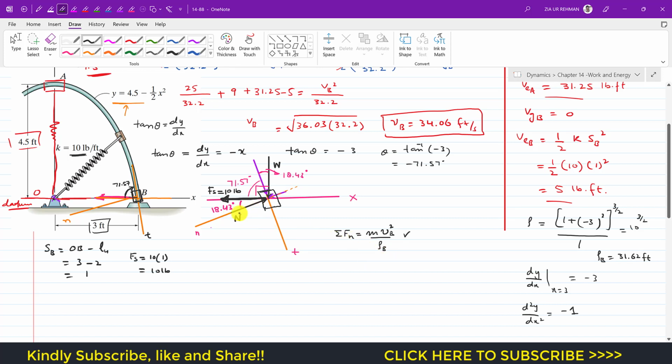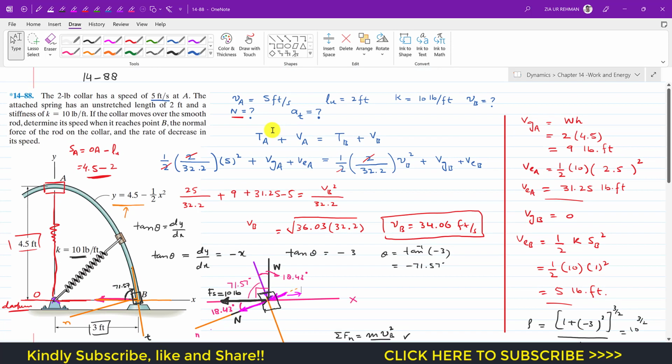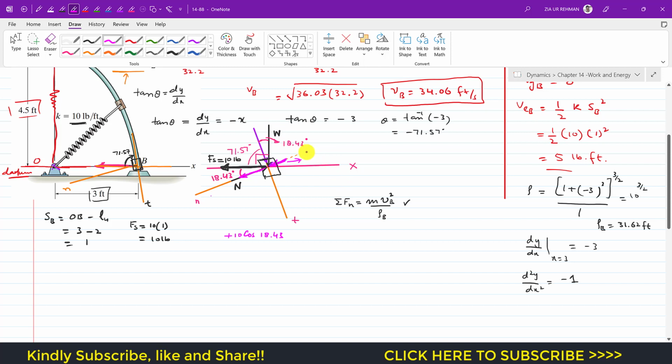So now we can apply this equation. The normal force is acting in the negative n direction. First let me resolve these forces. This spring force can be resolved into two components. One component is going to act in the positive n direction, like this. This is the cos component, so this is plus 10 cos of 18.43, and then this component of the weight. The weight is 2 pounds, it is given as 2 pounds, so this is 2 sine of this angle 18.43.